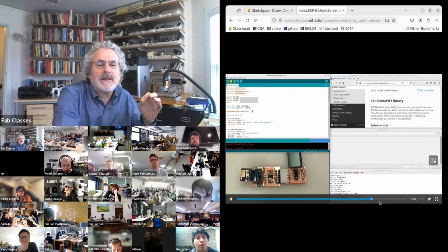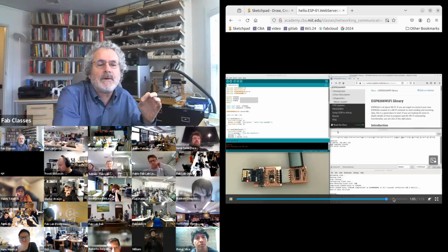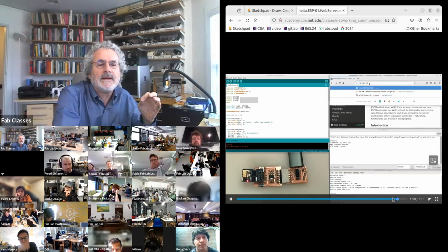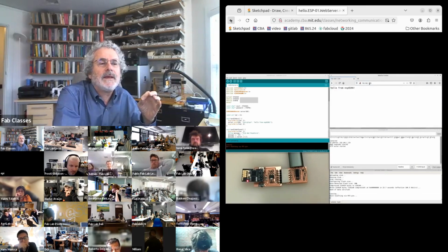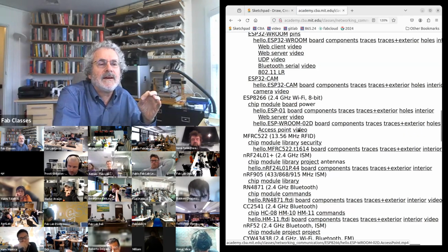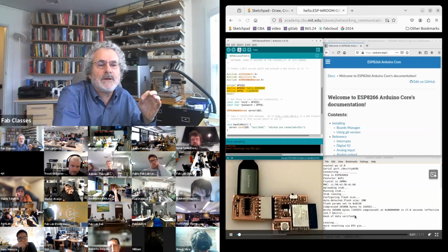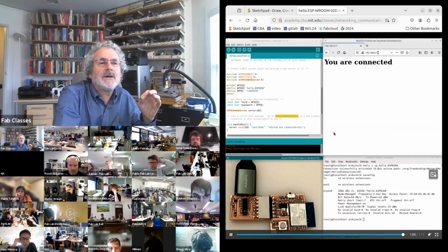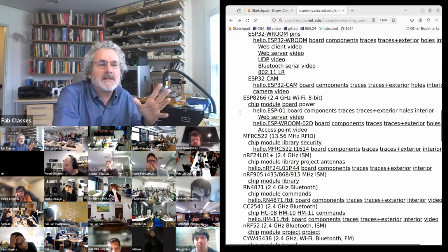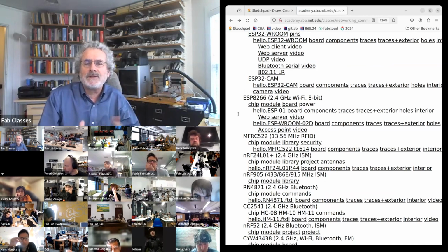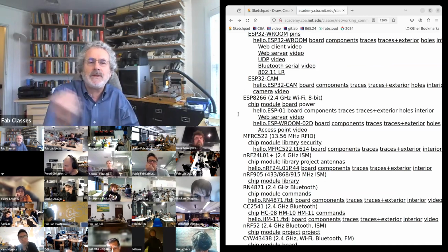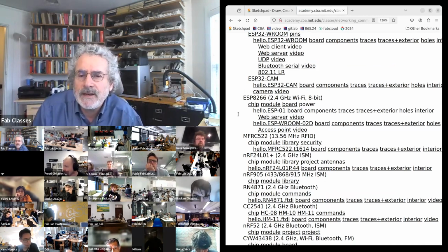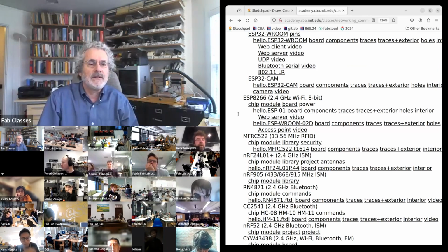In this version, I show web serving. And so it's serving a web page. In this version, I show it being an access point that you connect to. And so the shells generally are more convenient at this point, but the ESP01s are cheap. And if you just simply need to paste a Wi-Fi radio onto another project, they're an easy way to do it.